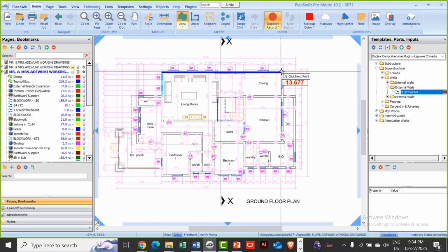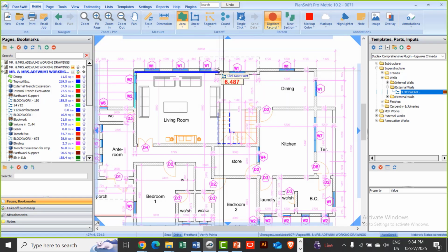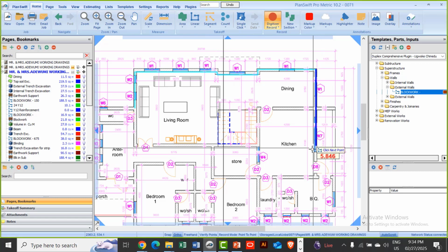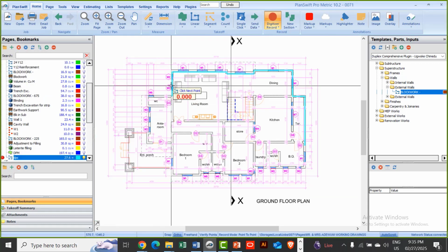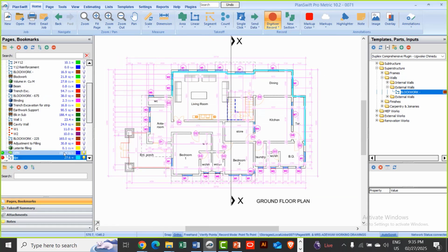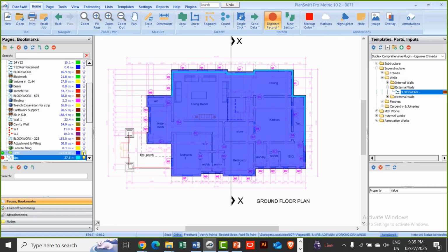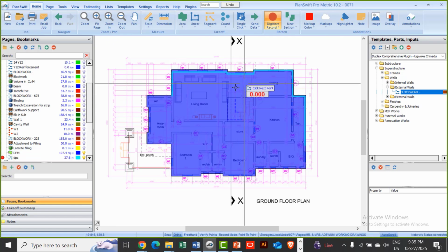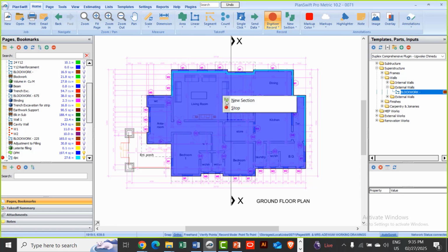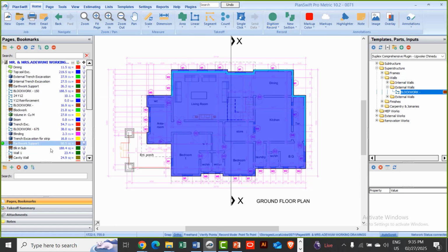Or you can even go to the place where you measured your gate, your perimeter, and just get that value, and then you can price in either meter or square meter, okay? So that is it for your DPC. Your DPC will be in this linear form, but your DPM is this one that covers the whole area. So you see the DPM and the DPC now. All right, I believe we understand that.